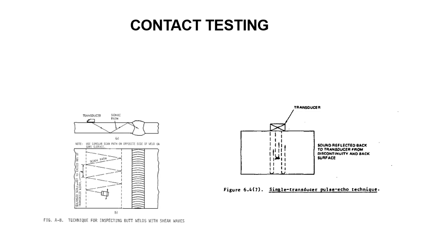Contact testing is divided into 3 techniques, which are determined by the ultrasonic wave mode desired: the straight beam technique for transmitting longitudinal waves in the test specimen, the angle beam technique for generating shear waves, and the surface wave technique for producing Rayleigh or Lamb waves.